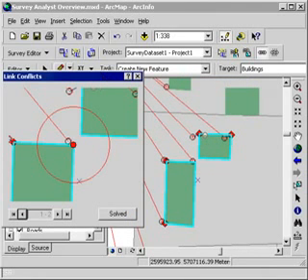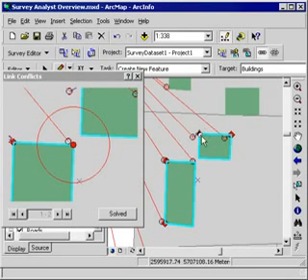Now you'll notice what happened. In this particular case, links were established for 2 corners of this building in the upper right, and links were established for 2 corners in this building on the left. However, there's a situation in the middle where one survey point is within the linking tolerance of 2 building corners.